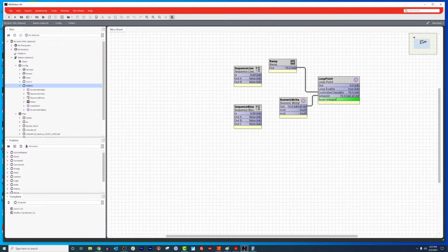If I can answer any questions, I really hope this demystified PID loops. I saw some people sharing some YouTube videos, and they were like crazy science and logarithmic algorithms, and I was like, holy crap, folks, it is not that difficult to do PID loops. It's two things. You got to figure out your prop band, and you figure out your integral value, and that's it. And maybe you add a bias. But I mean, don't overthink this stuff.